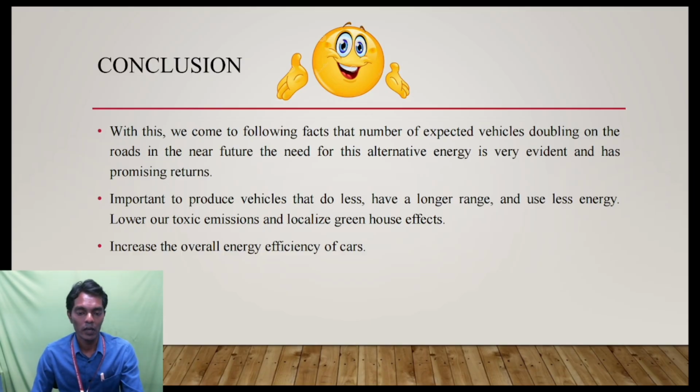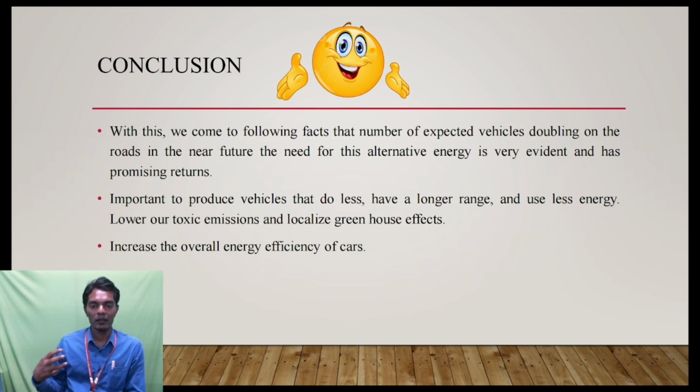and another important thing is quick charging. In order to charge your car quicker, you have to increase the charging current or charging power. But when you increase the charging current or charging power, your battery will be taking very high current, and when your battery is taking high current, heat is developed inside the battery.